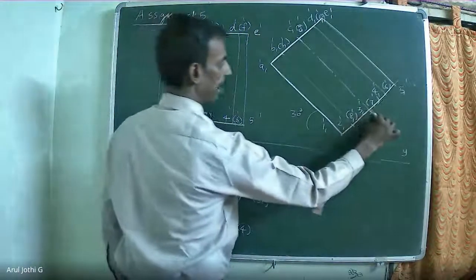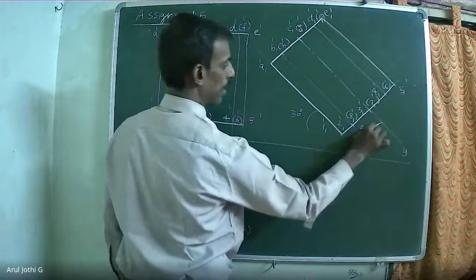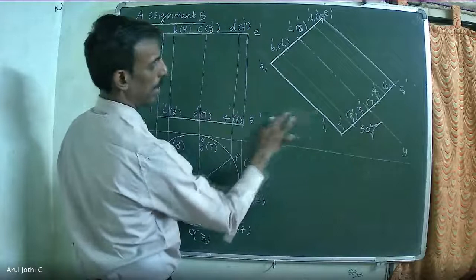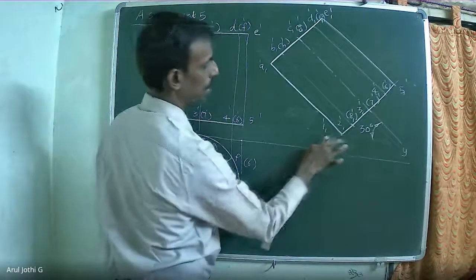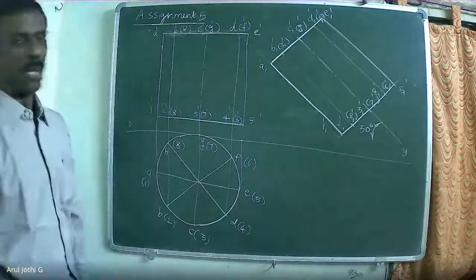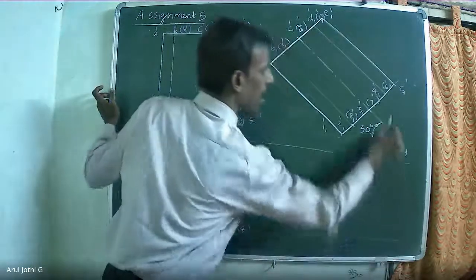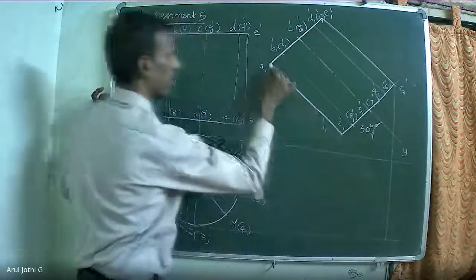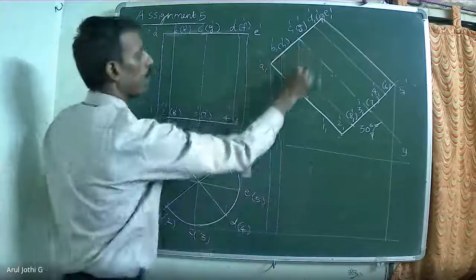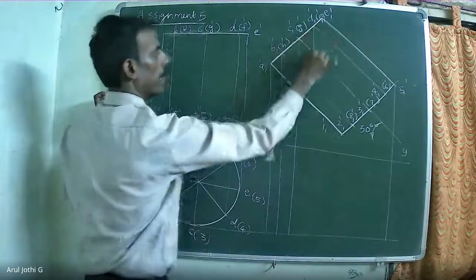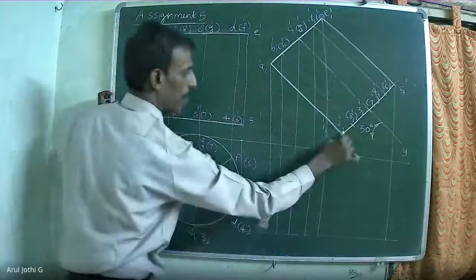Now extend the axis line downward and mark the given angle. Axis inclination is 30 degrees. So here you have to erase the given angle. Similarly, extend this construction line also. Now we are going to draw the apparent top view. So draw the vertical and horizontal projector lines. Corresponding points will be intersecting and form the shape of the apparent top view.